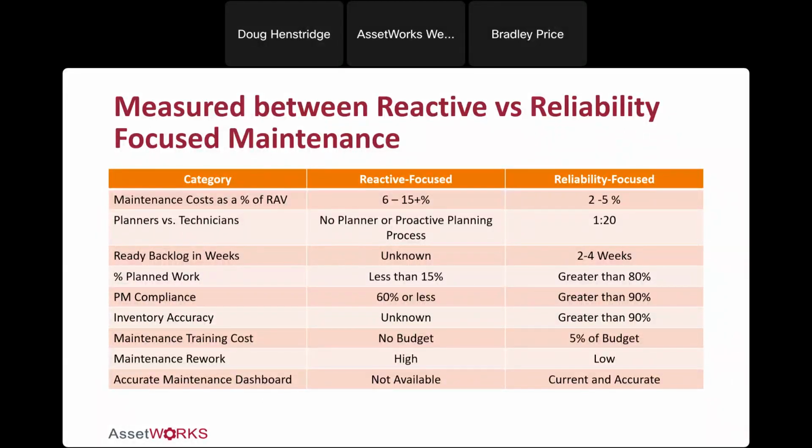PM compliance. And when I talk about PM compliance, that's PMs being completed plus or minus 3 days of their due date. It's often under 60%, maybe less than half, whereas the goal should be to have that be 90%.